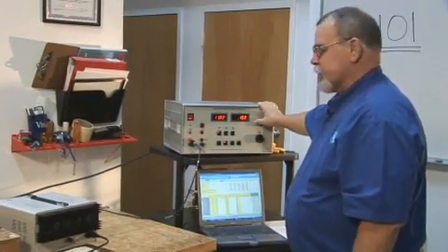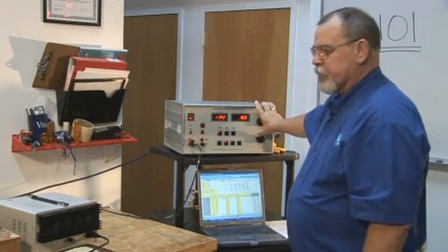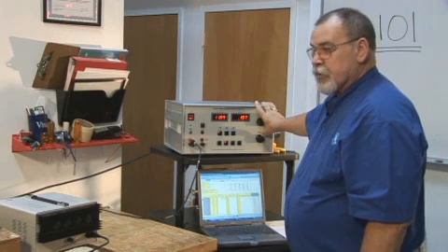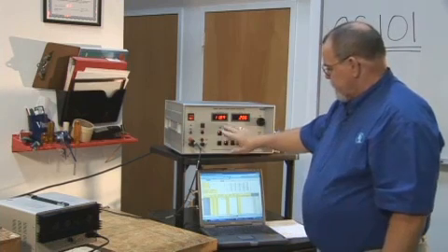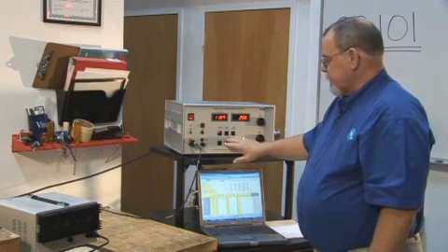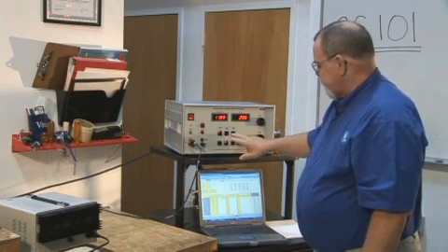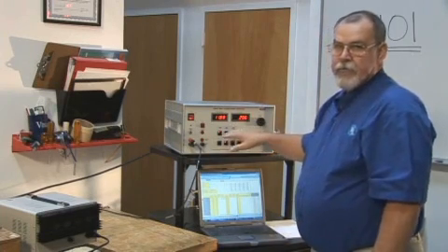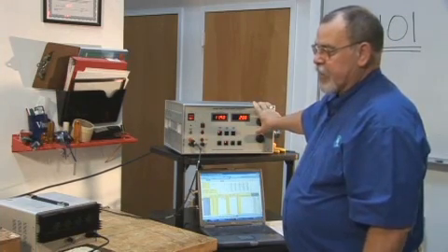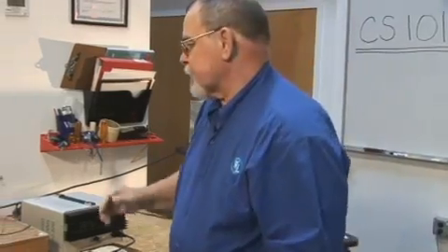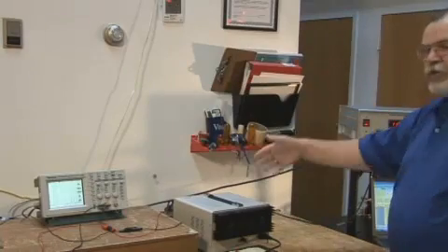So we kind of do this, and we keep doing the frequency test, shifting the frequencies until we get through all the frequencies. And this is a slow process. By the way, the generator here was built for CS101 testing, and you can sweep a band of frequencies or all the bands and let it automatically go through it at the correct rate. Now, you need to verify that it is working right for the sweep rate. But we're constantly monitoring our activity on the oscilloscope, our test level, and EUT performance.